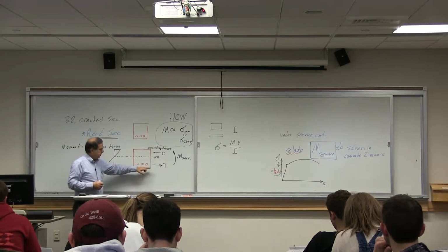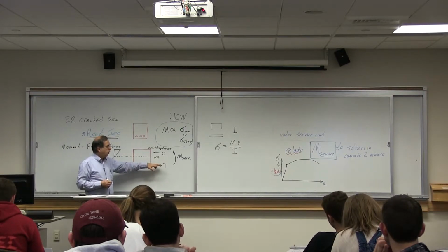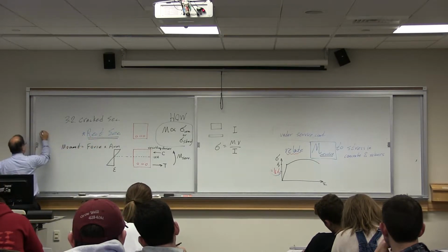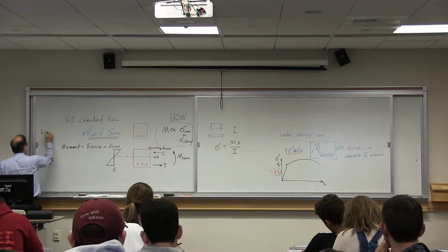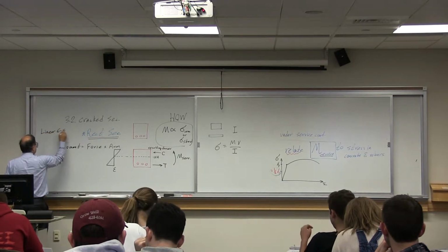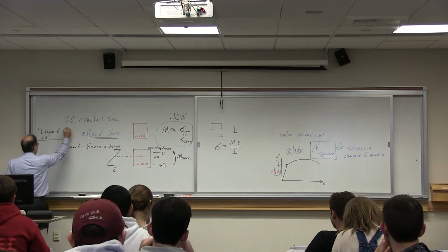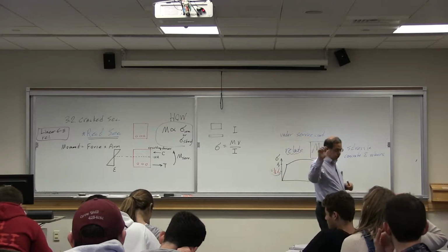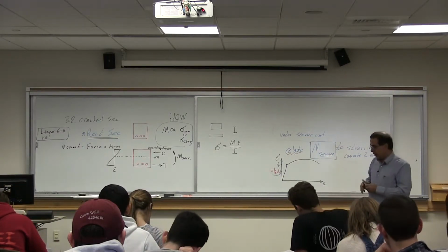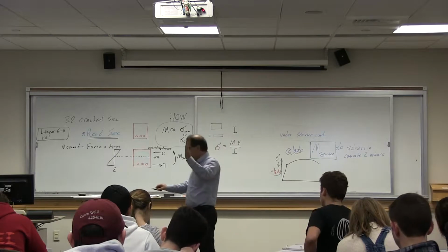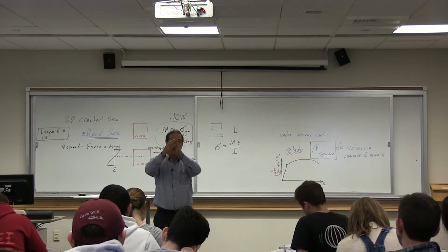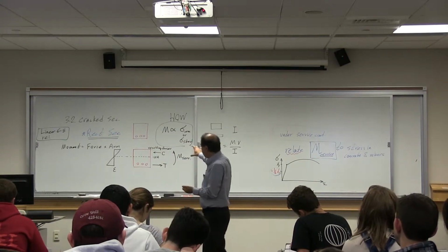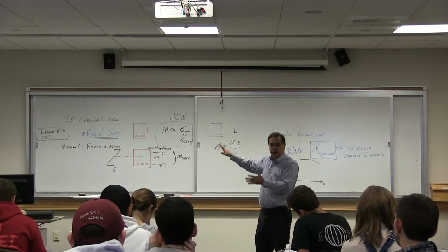The rebar is under tension. What we know is, I guess I erased it, linear stress strain relationships. So you apply the moment to the section as we discussed before. If this is the section, and you apply the moment, the top part goes to compression, the bottom part goes to tension. They generate this coupling force that would resist the moment.